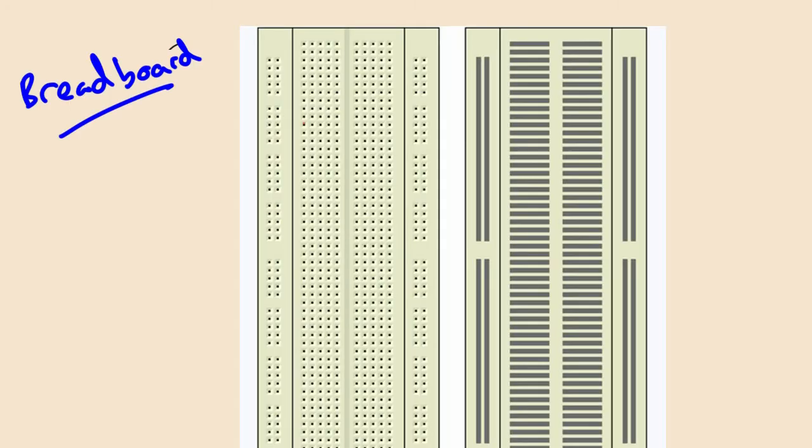The last thing that we're going to look at before we look at putting together this hardware and the code is our breadboard. To build our hardware in the labs, we're going to use a breadboard, and a breadboard looks something like this. You can see all these holes, and this is where you can make connections with components. All of these holes are connected horizontally as seen here. So this middle section, all the horizontals are connected.